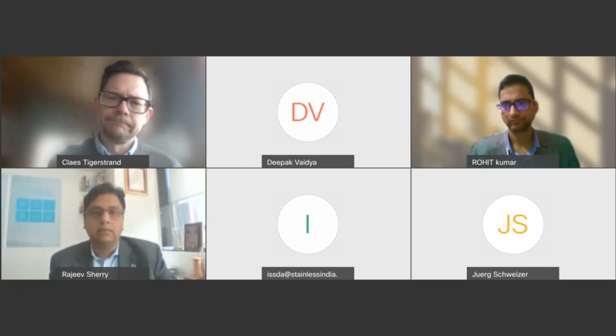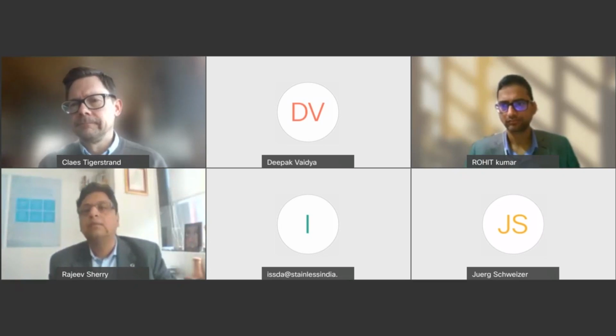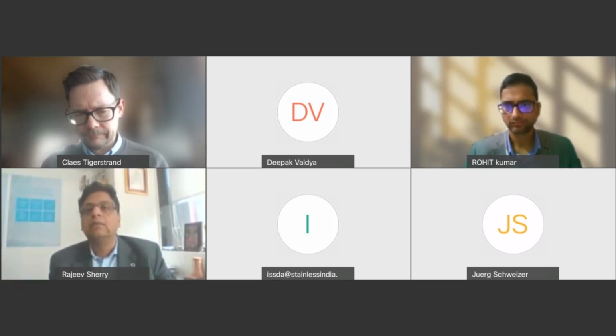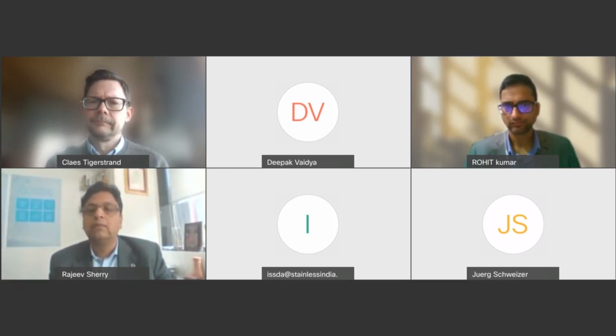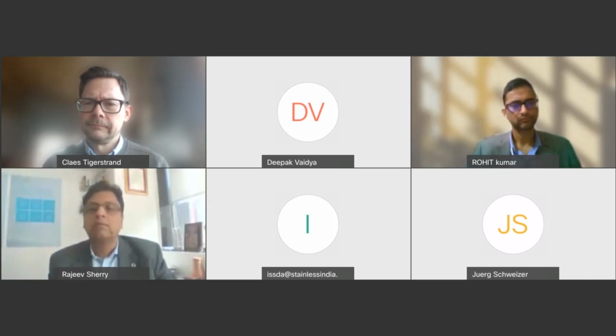Another question, Mr. Shikhar. Which grade of stainless steel can be used in mobile tower application? Okay, it depends upon where you want to install the tower. If you are talking about some coastal areas, then surely duplex is the right choice, because normal 316 and 304 will not sustain because of the chloride environment.